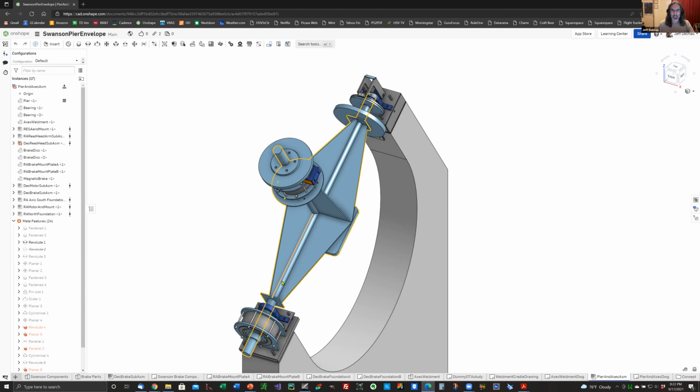So that's one type of error. Another type of error is that gears are never perfectly circular, so you tend to get periodic error, which is a sinusoidal error, where the gear may go faster at one point and slower at another. We saw that kind of error in our system, and that tends to make stars go back and forth such that the average position of the star is right. In other words, the mount will track the star really well, but it'll have little bloated stars that are actually short little lines because you've got error going back and forth.